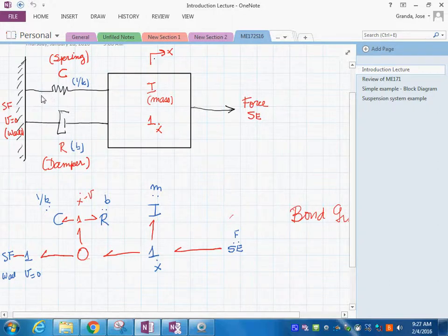The way it works is that we need to have, what did I call it, a collection graph or junction graph or bond graph, a way that represents this connection. We represent the source of effort for the forcing here, and this one junction is telling us that in this system the velocity x dot is common to the forces of all the other elements.